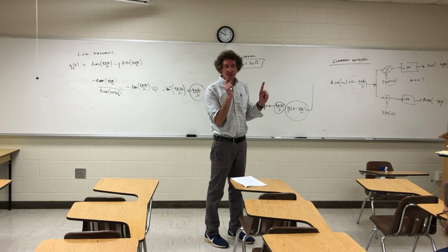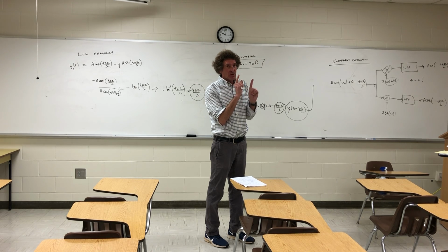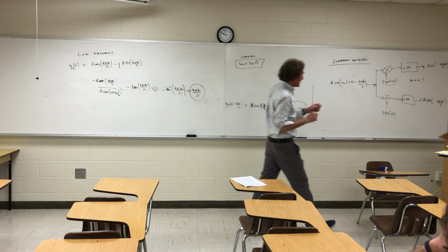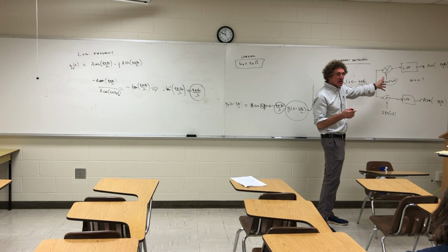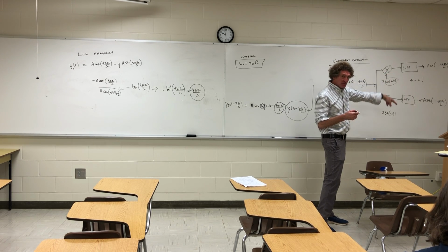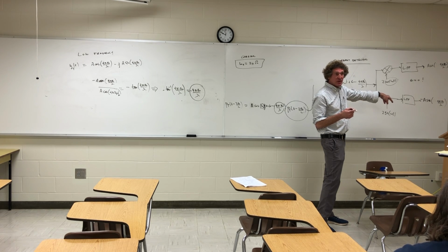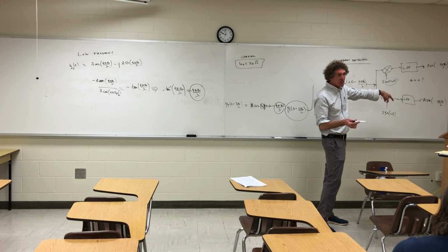Now this can be accurate to a quarter of a wavelength with coherent processing. This right here is a lot more complicated than I made it out to be, but that's really what you're doing. You're multiplying by a sine and a cosine, a 90-degree phase change, so that you get precisely a 90-degree phase change after it goes through the low-pass filter, and you can extract R naught. That's why this is so valuable. And I didn't say that last time. I want to make that clear.